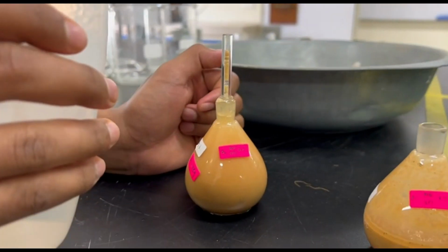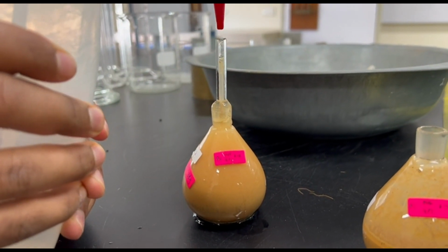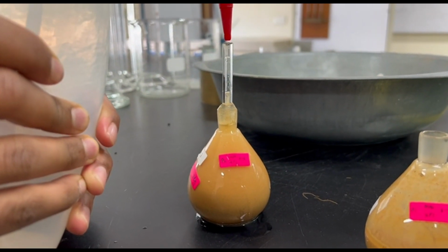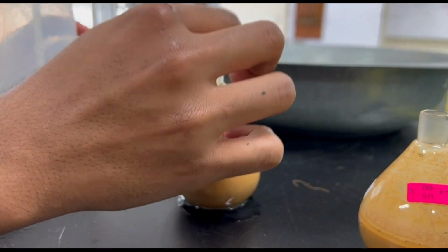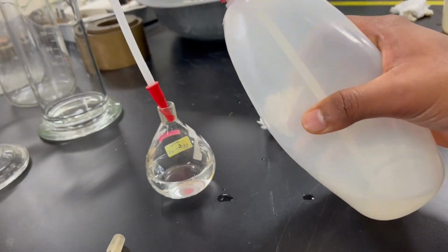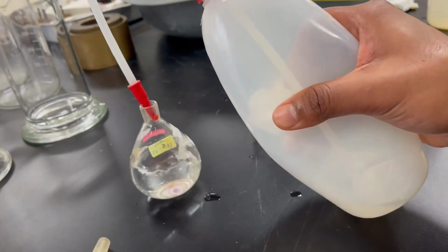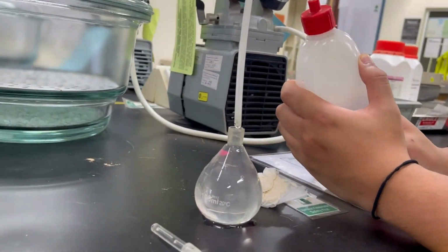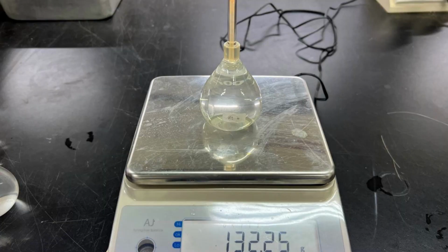If the capillary of the stopper is not full, drops of distilled water are filled in the capillary. The bottle filled with water and soil samples with stopper was weighed and recorded. Then, the bottle was emptied and filled entirely with distilled water. The mass of density bottle with water and stopper was weighed and recorded. Finally, the steps were repeated for another 2 observations to obtain an average specific gravity of the soil sample mixture.